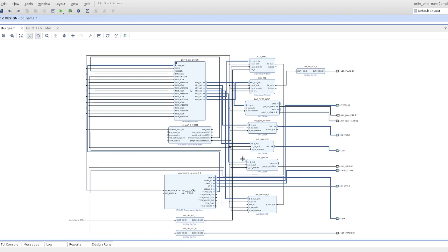Another part is the AXI GPIO, which is used to test the implemented partial reconfigurations. These can be controlled by the user over a web interface. The last part are the dynamic clocks, which can also be programmed by the Zynq to provide various frequencies and maximum flexibility to the user.